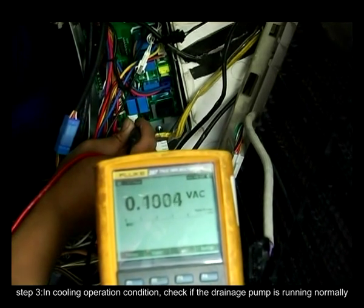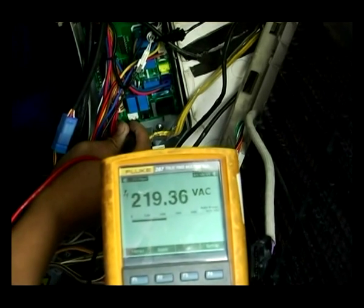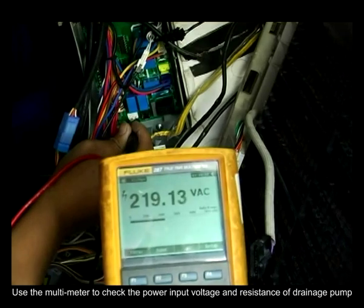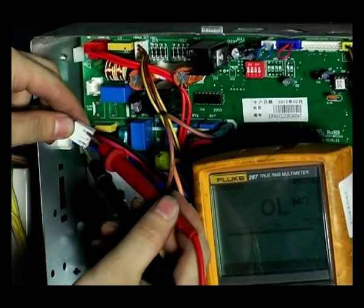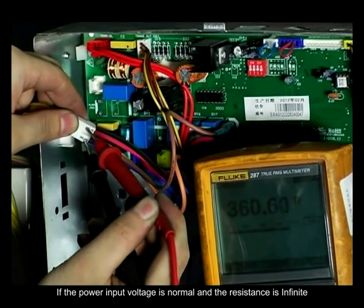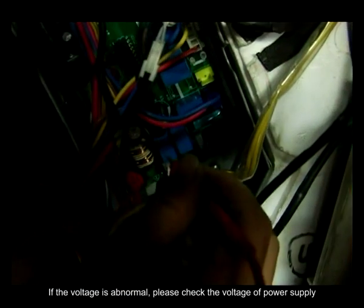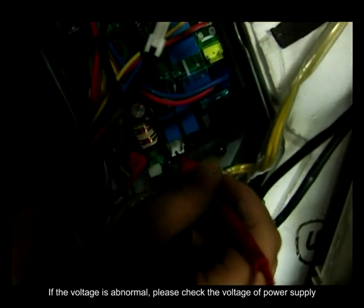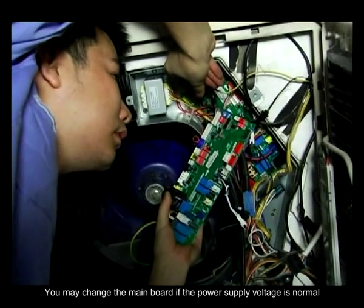Step 3. In the cooling operation condition, check if the drainage pump is running normally. Use the multimeter to check the power input voltage and resistance of drainage pump. If the power input voltage is normal and the resistance is infinite, that means the pump is damaged. If the voltage is abnormal, please check the voltage of power supply. You may change the main board if the power supply voltage is normal.